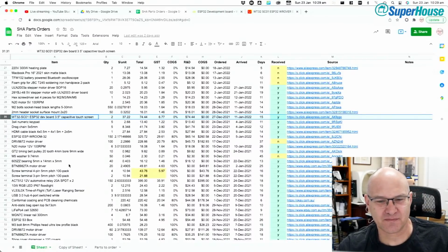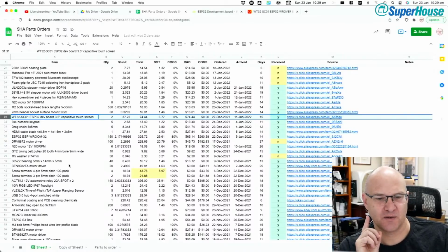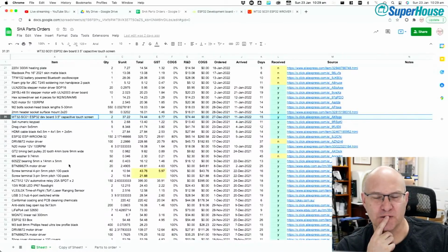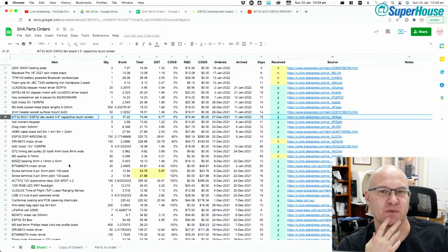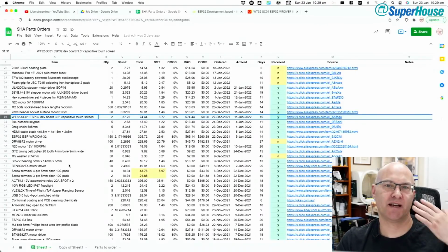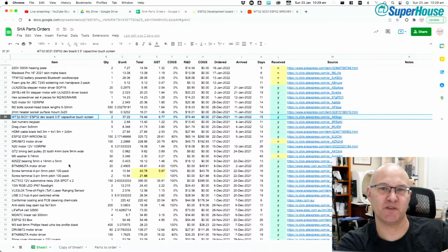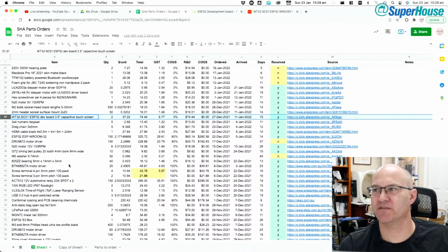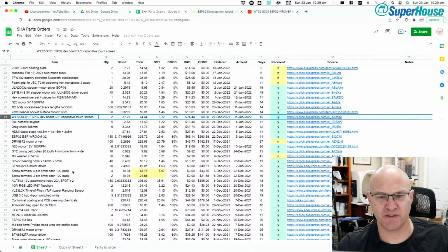Oh, Austin said the missing part is the U1. It's an IR proximity sensor, VCNL3020. That is cool. So yeah, not a camera. I think a camera would actually not be that useful in this situation, but a proximity sensor, that is really useful. So you could have the screen asleep, and as your hand moves up to it, it wakes up. Very, very cool. If we can retrofit that proximity sensor, that would be nice.